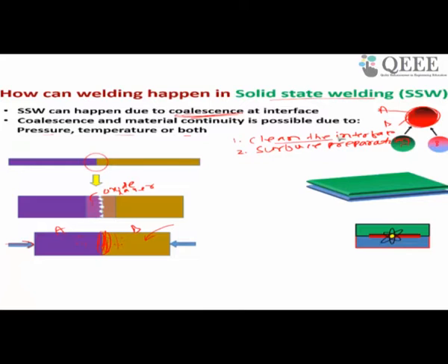First, you need to clean the surface, then you have to prepare the surface, because if you have an oxide layer, how to prepare? You have to use emery paper, remove the top layer, then you have to use some blasting, grit blasting, or something you need to do to remove the top layer. Or by using some steel brush or iron brush, you try to remove the oxide layer. So surface preparation is very, very important. That is the next step.